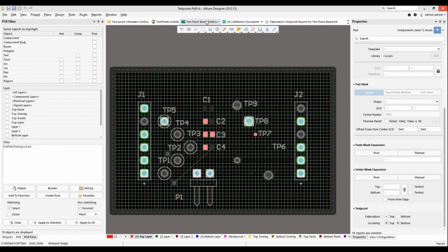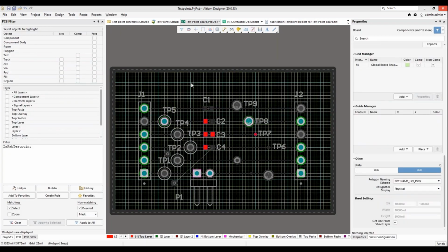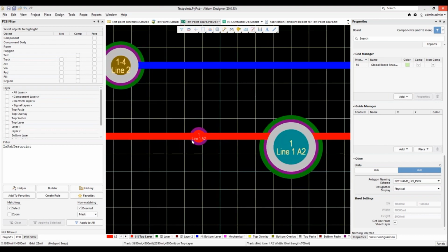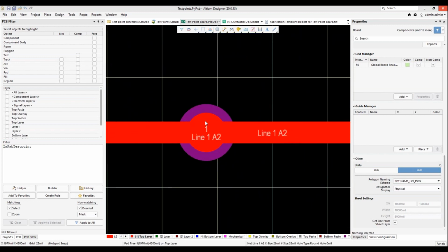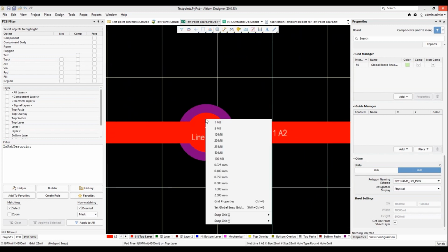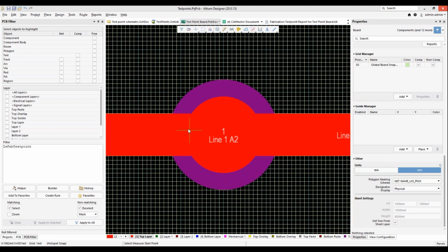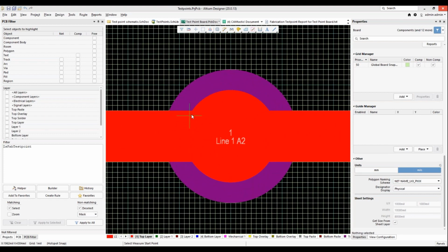The last thing I want to talk about here, because I know my time is getting on, is I want to talk a bit about signal integrity. So let me jump back over to the board. Let's do a Shift-C to clear this. And let's look at these two here. So these are samples of embedded. This one over here is pretty small. And if we change our grid, I'm going to hit the G key, drop this to 1 mil, Control M, just to give you a quick look at this, as long as the hotspot doesn't pull me in over here too badly.